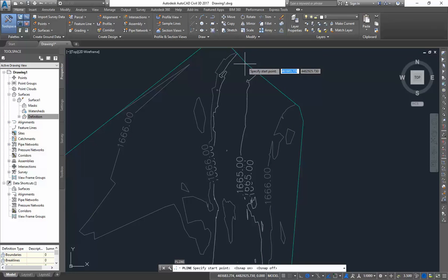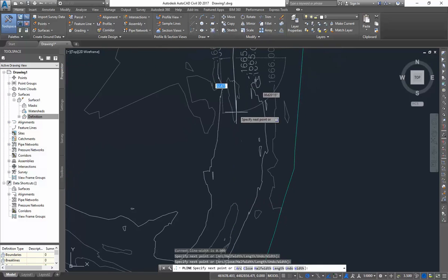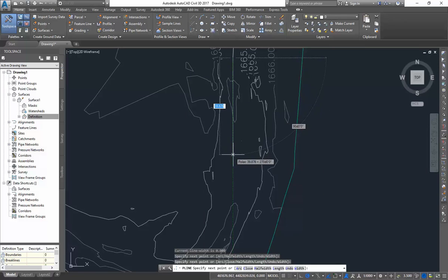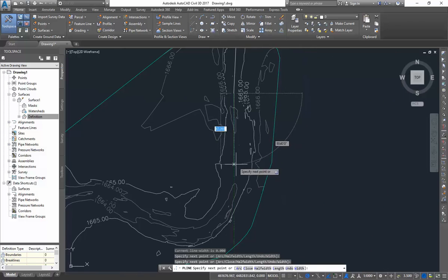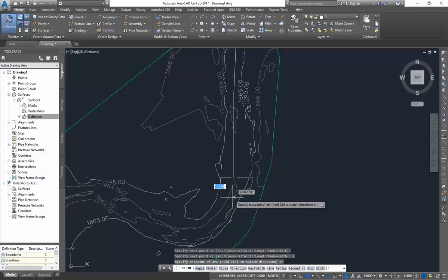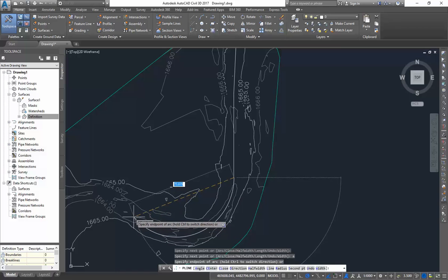So I just want to go through and draw. Polyline is going to ask for a series of points, just various line segments. If you look down at the bottom, you'll see that a polyline has some commands within it. It will default to just wanting to do line segments. So if I wanted to approximate, up here where I have a large arc, it'd be pretty choppy for me to go around this bend. I can see down here if I type in the word A, it'll convert to an arc. So I can approximate the river bend that way.